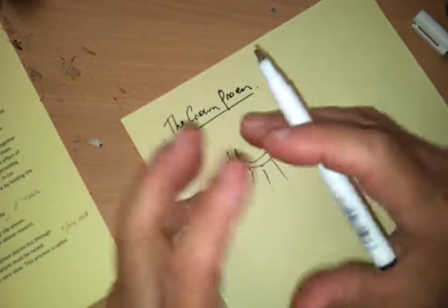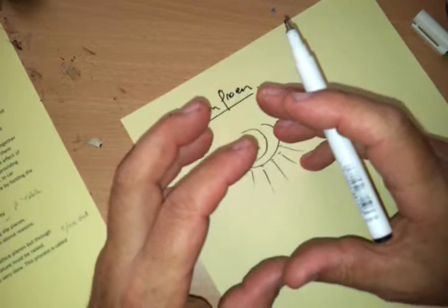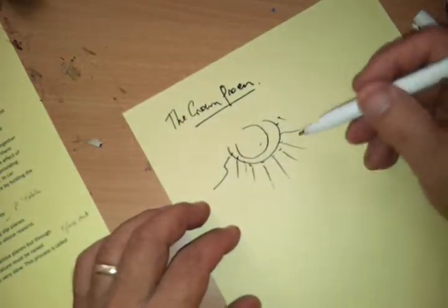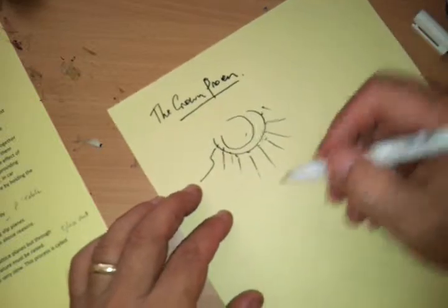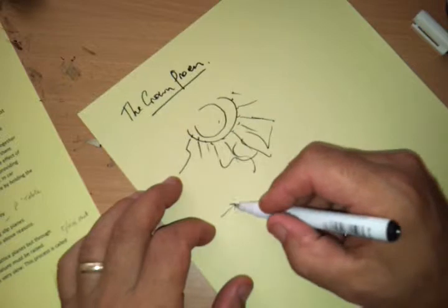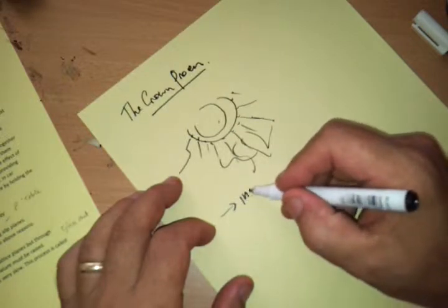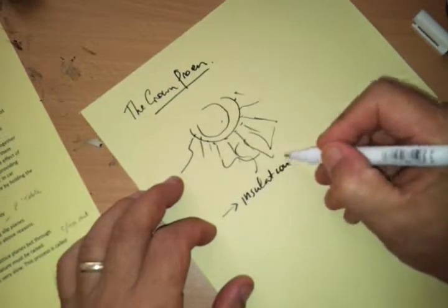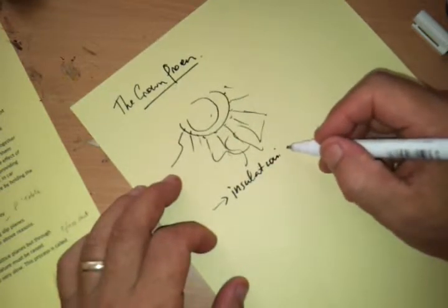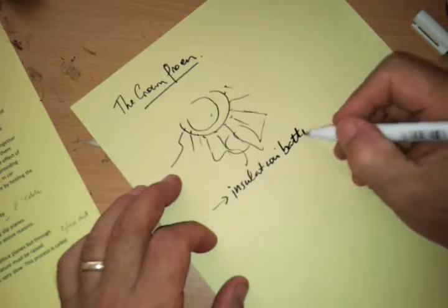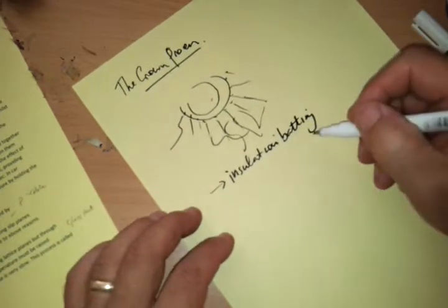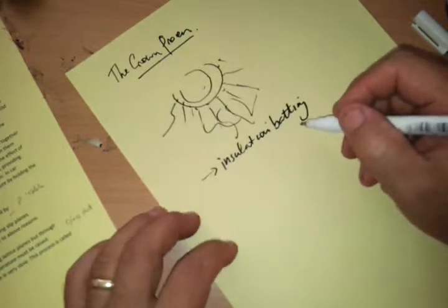And further, to make the placement of these glass fibres even more random, compressed air is blown into them as well, and this crown process creates this intertwined kind of mat that's used to create your insulation bats. Sometimes you'll see rock wool, it's called rock wool, or you'll get pink bats. So the insulation batting is made using that crown process. Okay, and they can be pressed and trimmed and cut to shape.